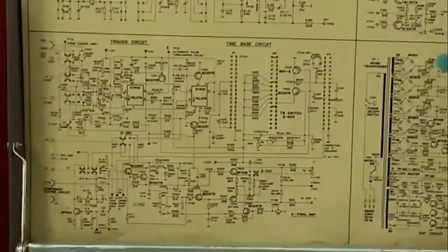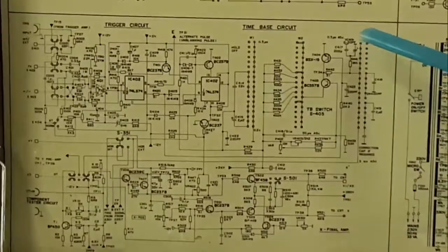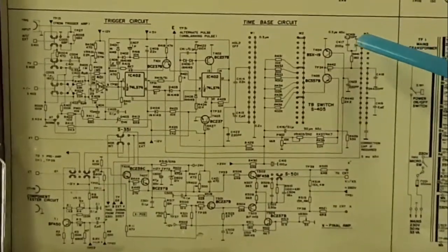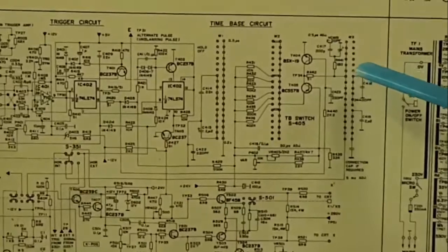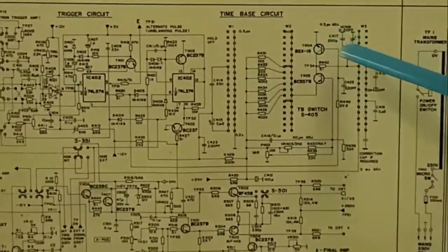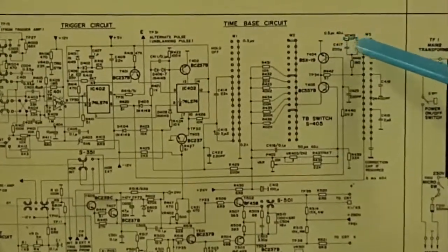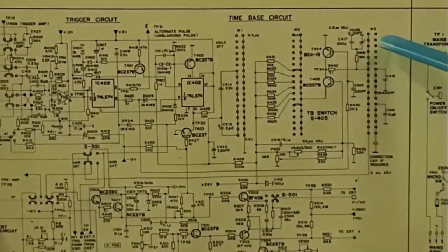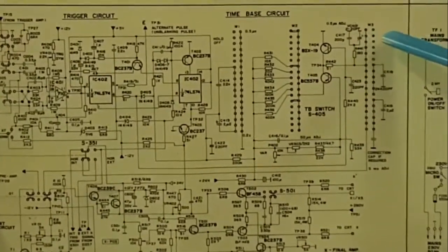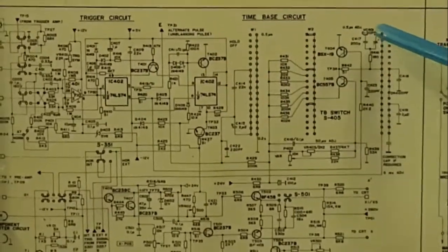Similarly, if you look at the time-based generator circuit here, the role of the time-based generator is to provide the varying values of the sweep signals. The sweep is a modified form of the triangular wave where the retrace time or flyback time is 0, so that you can synchronize the incoming input signal on channel 1, denoted by the test terminal. That signal can be synchronized with the help of the varying value of the time base.